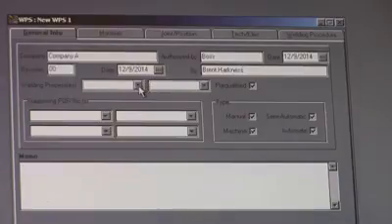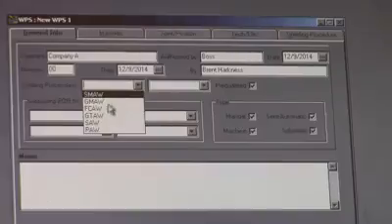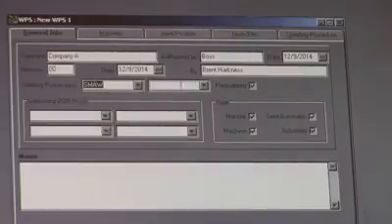What we're going to do is a stick weld, a pretend stick weld, so it's going to be the only process we're going to do here, SMAW. And you never leave any of these blank. They always have to have something in them, otherwise it leaves a doubt in the mind of whoever's reading it. Was that left out or was it purposely left blank? So I always put NA, not applicable.